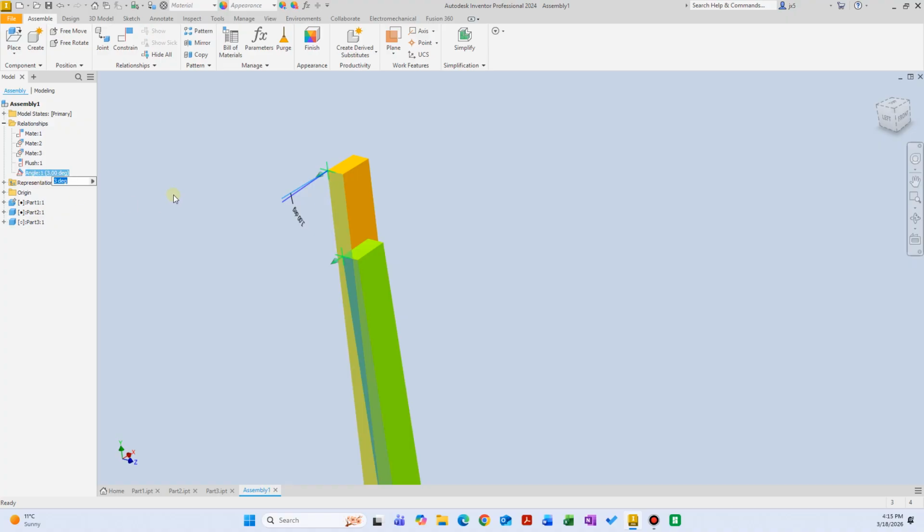So when you click on this, a lot of people try to delete this by hitting the delete button on their keyboards, and they accidentally delete this 3 degrees. So just to get away from that, just right click and hit delete. That way you can delete that constraint, and this goes back to moving left and right.